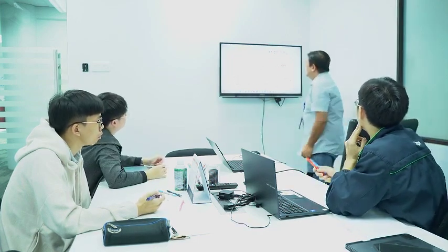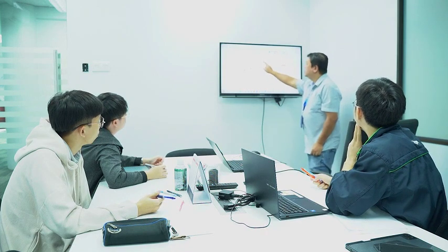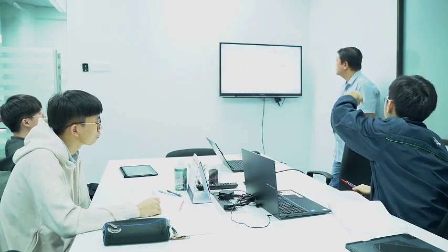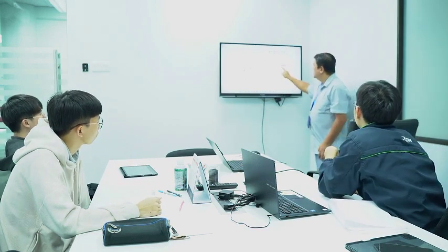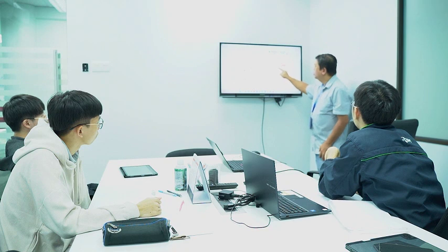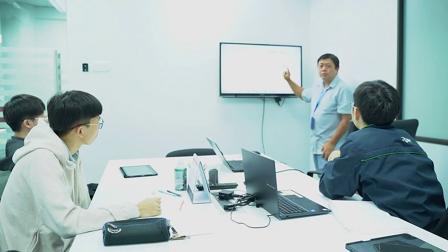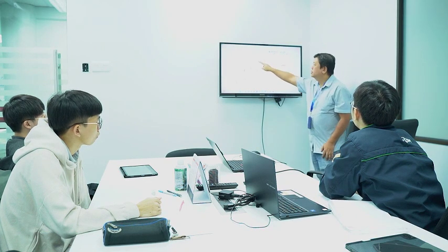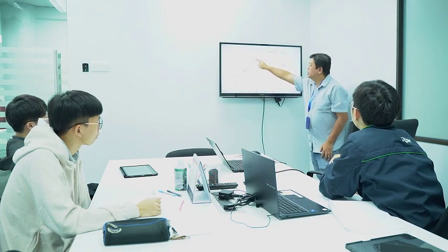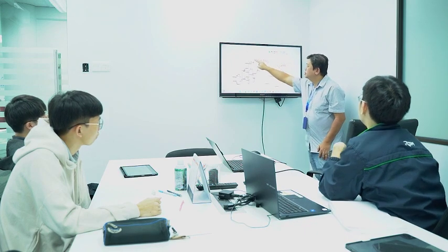It's an integrator. There are 2 poles. The first one is 1 over S. And 1 plus SRC is a normal RC. So from the graph just now, the first one shows negative 20. This is the origin pole, 1 over S.